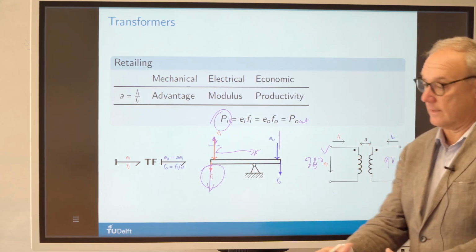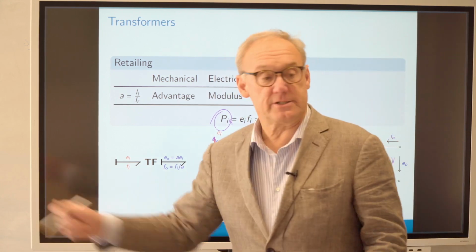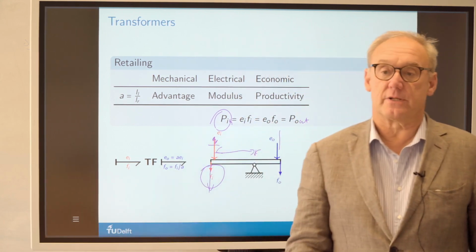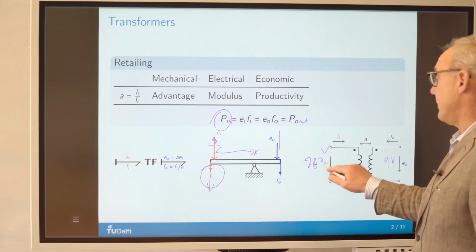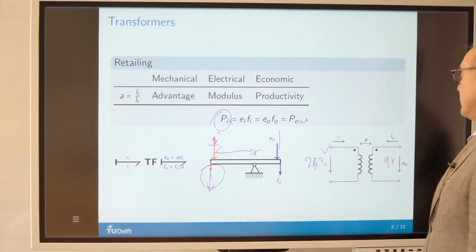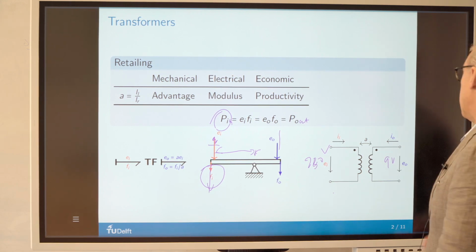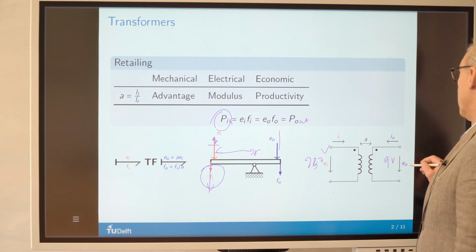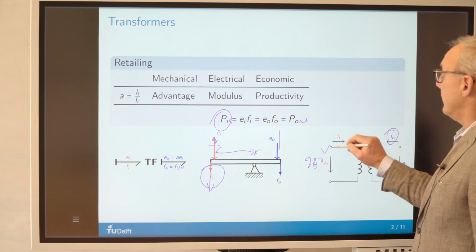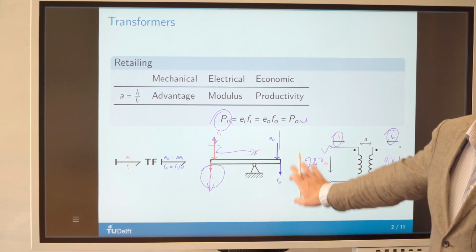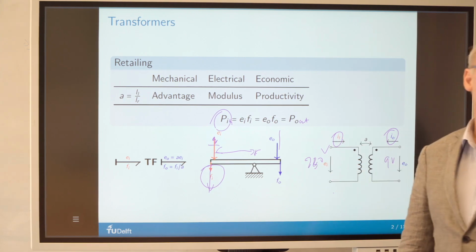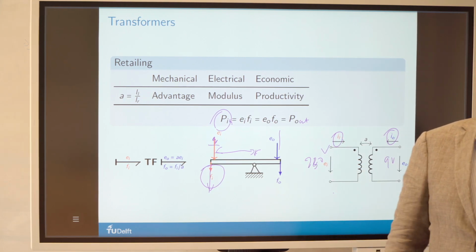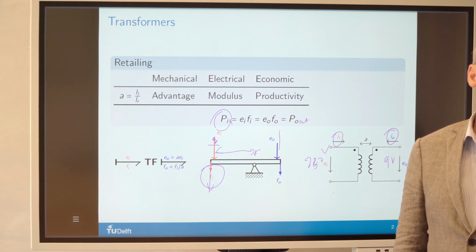And in this little block, you see these things at the end of your cord, there's a thing that's called a transformer. It will drop the voltage from 230 to 9. And at 9, you can draw a lot more current than you will be drawing at 230. Why? Because the product of the current times that voltage drop is the power, and it's got to be a constant. Okay?